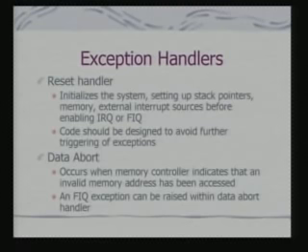So, how do you design exception handlers? Typically, the reset handler initializes the system. It sets up stack pointers, memory, and external interrupt sources, and initializes the peripherals before it enables IRQ or FIQ, because you would not like to have spurious interrupts before the external devices have been initialized.